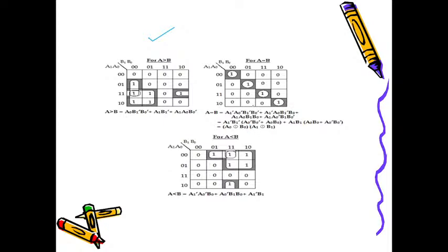Even after making a grouping in your K-map, again you have to apply certain mathematical rules so as to get a very simplified expression, because we have special derived gates for these things. Instead of making use of an OR gate, inverters and 4 AND gates, I can simply make use of 2 XOR gates.